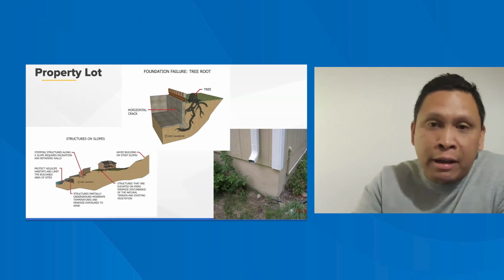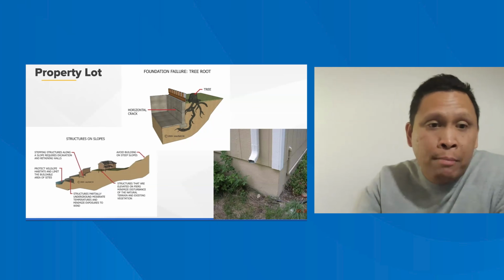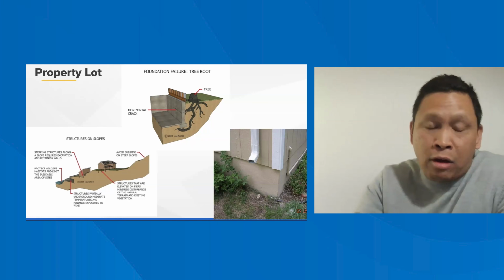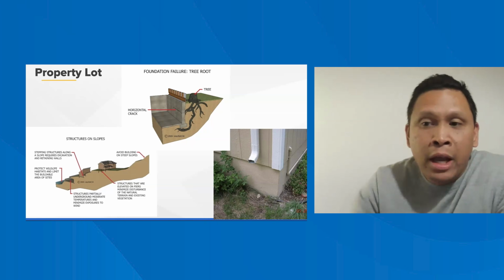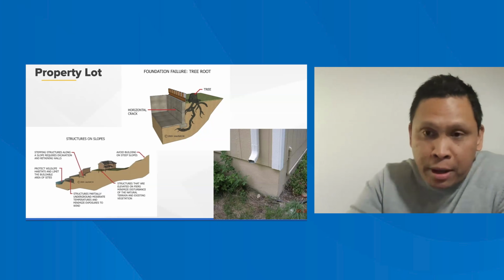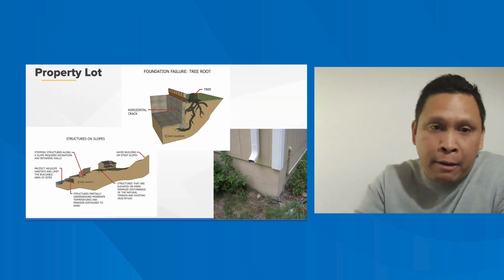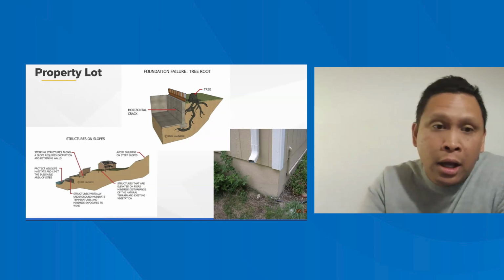One of the things that's very important, that we don't often see on a finished home, but can see if we're looking at a home before they hang the drywall, is anchor bolts stationed around the entire bottom sill plate. They're meant to help hold down, or pin down, the wall, but also help prevent the wall from what we call racking. That's the movement from side to side.